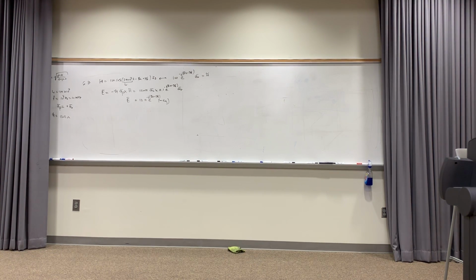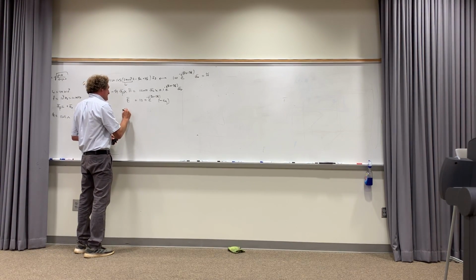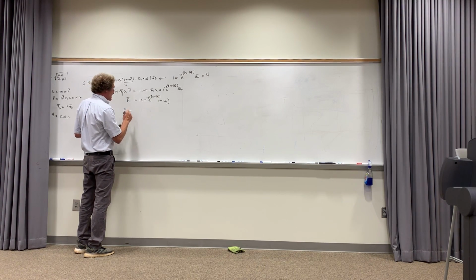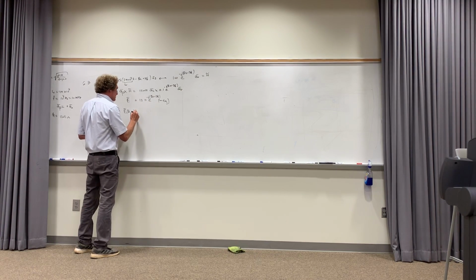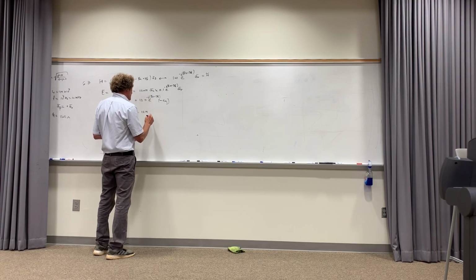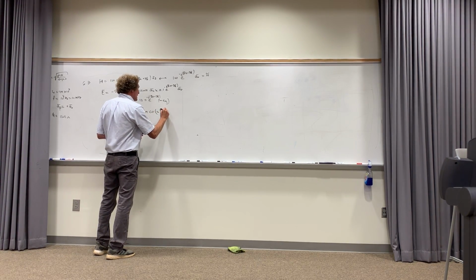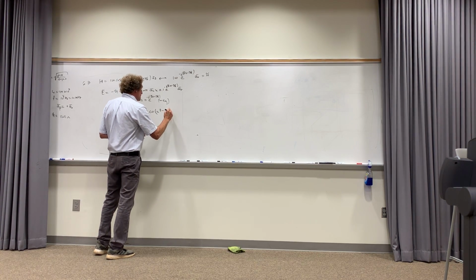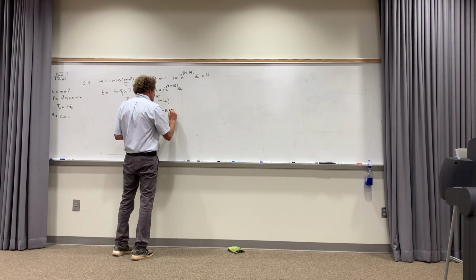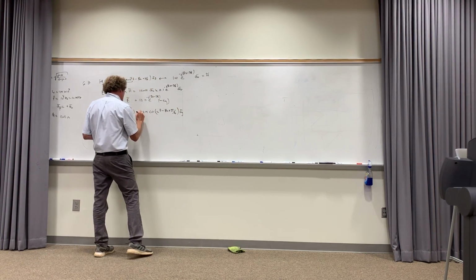So can you just turn that back to instantaneous form? What do we do to get instantaneous, in a nutshell? If we want the instantaneous, it would be a function of x and t. We take that magnitude, 12 pi, right? Then what are we going to do? It's cosine of omega t minus beta x, plus pi over 4. And it would be in the AY direction, and this would be minus.